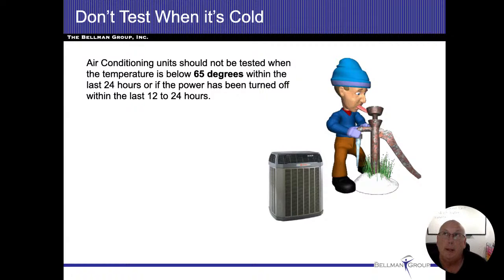All right. Now, the reasoning why we don't want to test air conditioners at a lower temperature, I need you to go back to your memories a little bit when I showed that compressor out there earlier. An air compressor can only compress air. All right. If I try to push liquid through that air compressor, then I'm going to damage that air compressor, plain and simple.